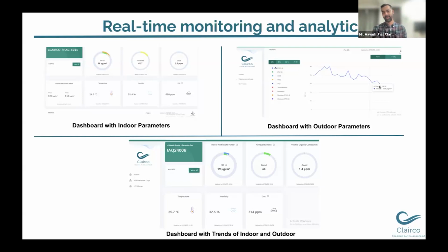So this is what I'm talking about. Having an intelligent system that measures these basic parameters, understands the fresh air systems, understands the filtration that you have, understands the occupancy levels, and then takes decisions on what needs to be done. What should be the VFD setting of your fresh air intake? When do you predict the filter needs to be changed?